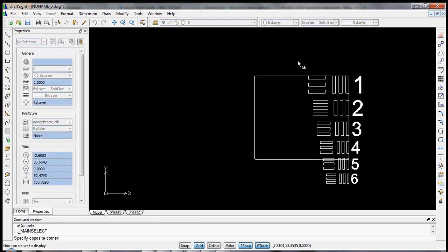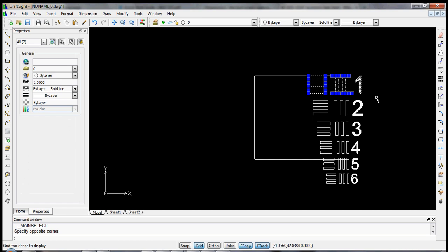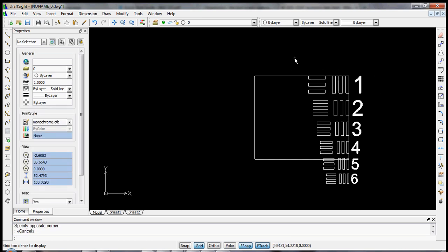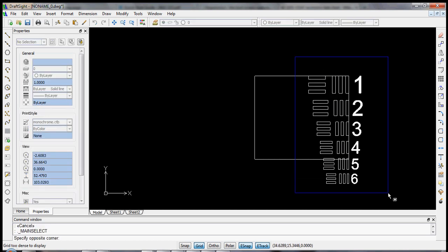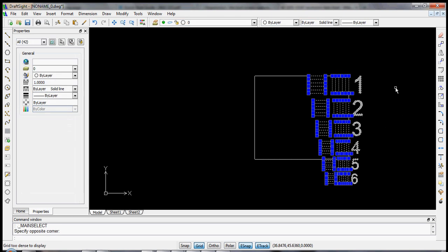If we did that the other way around, now we're doing it inclusively, so since we're not completely selecting that outer rectangle, the large rectangle, it won't be selected. So this is kind of useful. In this case, to select only the group, we can do this blue box selection. And let's try out the mirror command. That is this icon at the upper right.